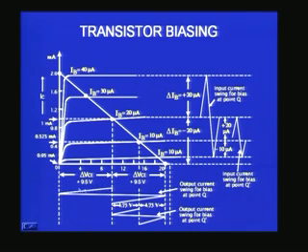This is a large signal which corresponds to the output. If I shift the operating point to some point here, you would find I will not be able to have perfect reproduction of the sine wave. If I give a large signal which is varying by 20 microamperes, you get only 10 microamperes available. Beyond that, there won't be any signal, therefore the signal will get distorted. That is the reason why I must always bias nearly at the midpoint of the load line. Then I will have equal excursion possible on both sides of the load line.